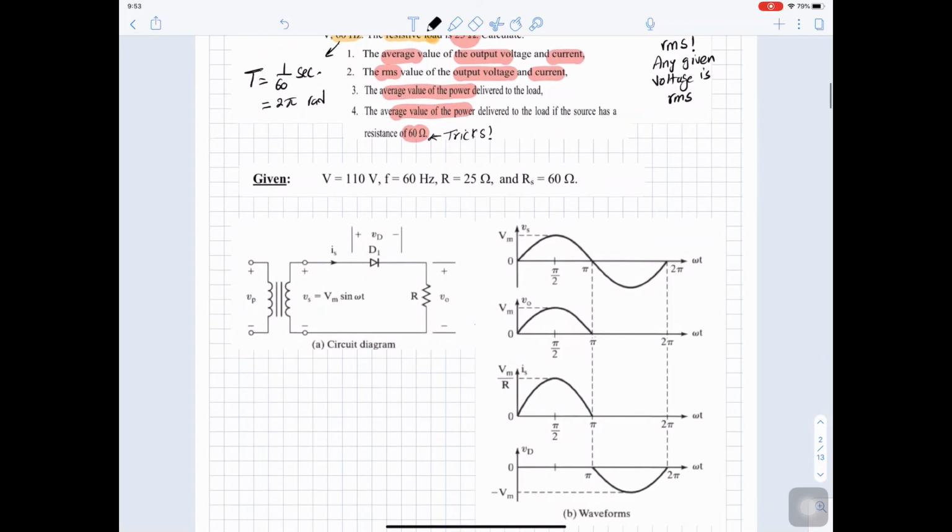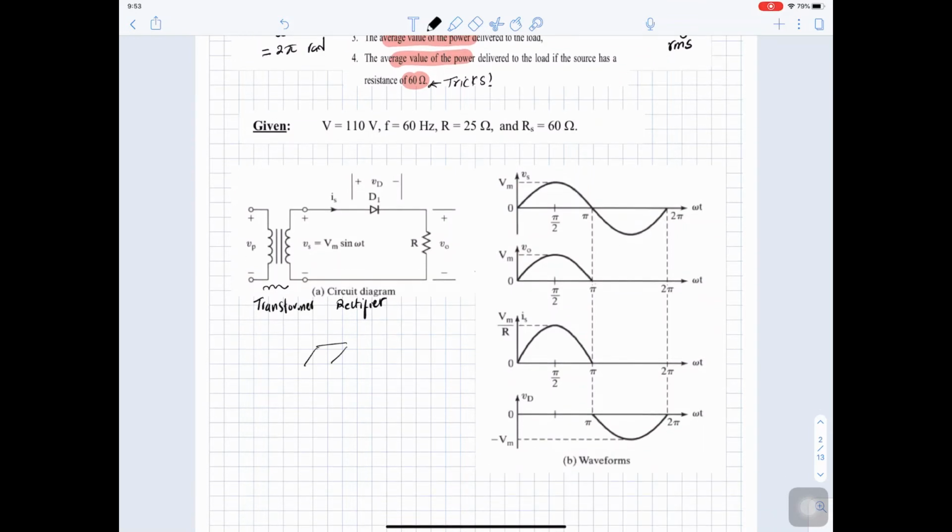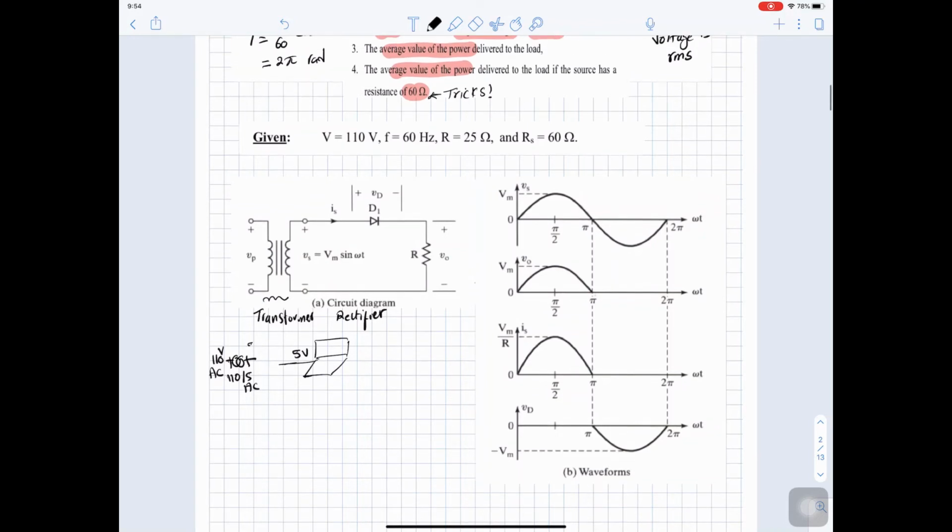Okay, so here we have the circuits that we studied last time, but usually this kind of circuits, the rectifier circuits, are supplied from a transformer. For example, if you need to supply your laptop, and your laptop needs say 5 volt, and the source you have at your home is 110 volt AC, what we will do is put a transformer. Say this transformer is 110 to 5 AC. So the peak value of the AC here, the maximum value, will be 5 root 2.